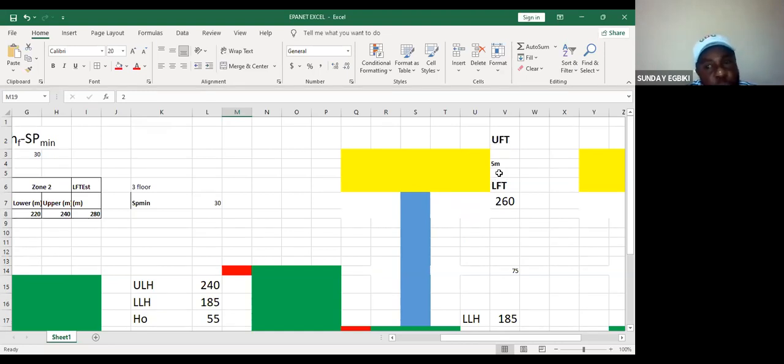But when you are distributing in the distribution water network, when you move it from here, it is 2 bars, you said. But at the consumer tap, that is where you expect the losses. The head loss there is 1 bar, which is equivalent to 10-meter water column. But here is 2 bar at the tank.